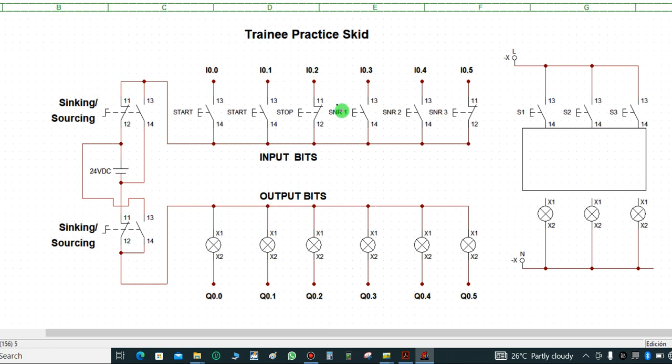So if that is my PLC, this connection I did before to the lamp, let me get the connection halfway and also get this one's halfway. How do I link that up? Through PLC. But I'll now have to create a tag here in which I link to my PLC. So this I0.0, I0.1, I'll tag them here. Okay, so this is three inputs I have and this is three outputs I have.